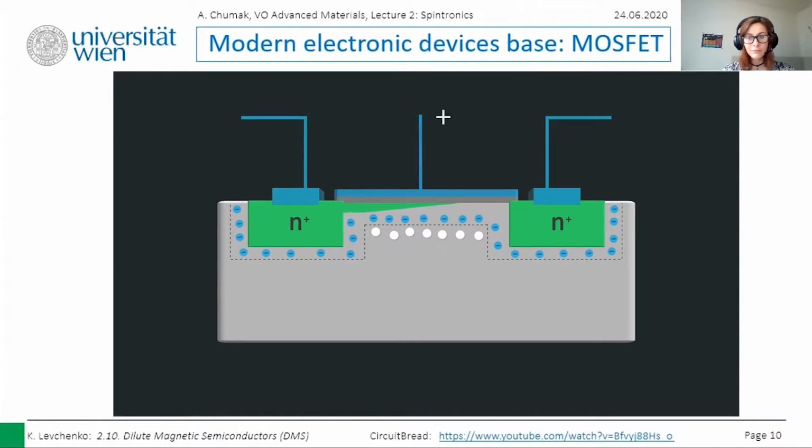However, as the gate voltage continues to increase, increasing the electric field, and finally passes the threshold voltage, electrons from the source and drain flow in and form an inversion layer of electrons that connects the source and drain regions. Now that they're connected, if a voltage is applied across the source and drain, a current will flow. The MOSFET is now operating in the linear or triode region.